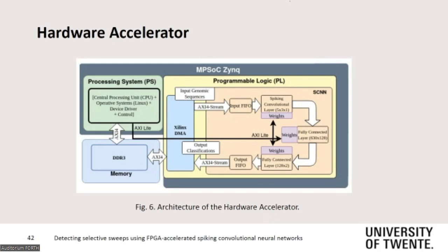So after that, we deployed our ICN architecture on a hardware accelerator. Here we train our ICNs on an ARM processing system, and then we load our ICNs, the weights of our ICN, onto the programmable logic via connection links.